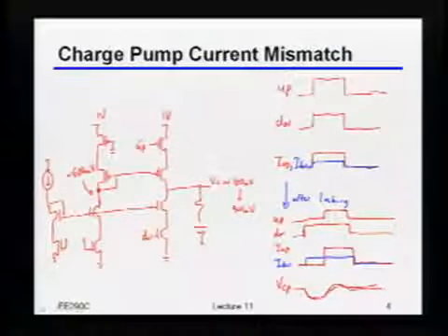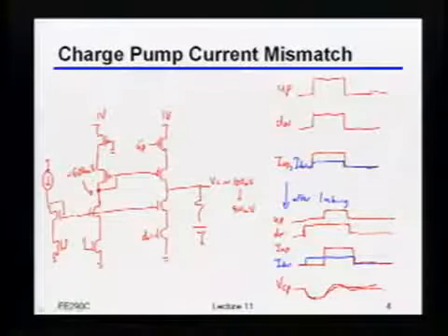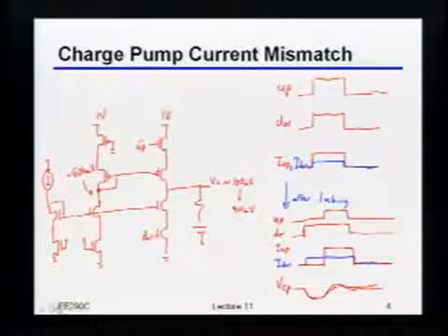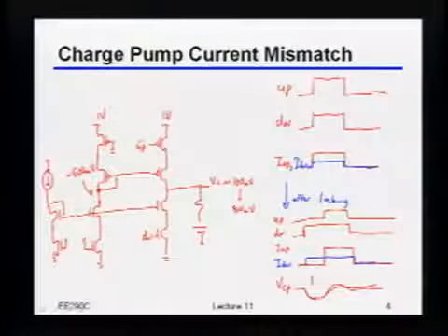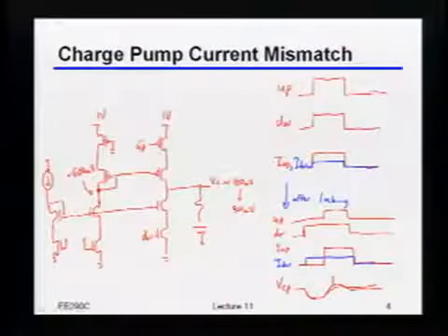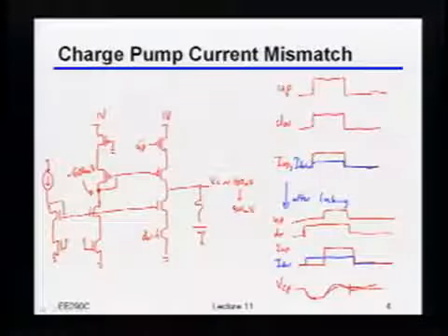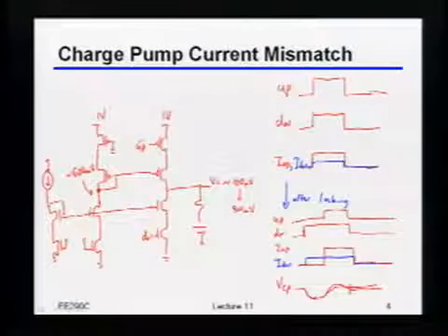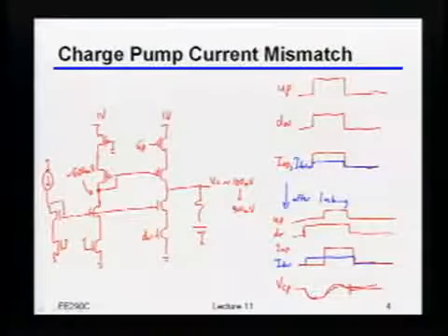Doesn't the loop filter that out? Well, no, because remember, this glitch is happening every reference clock, and this glitch gets fed to my VCO. All the VCO does is track its instantaneous frequency to whatever this control voltage is. So yes, you can argue that that's an integration.